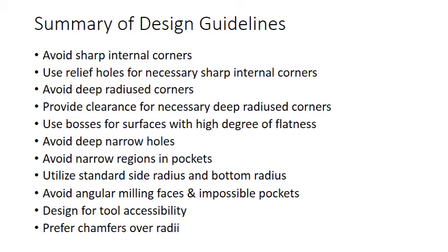To summarize the design guidelines: Sharp internal corners should be avoided. Relief holes for necessary sharp internal corners should be used. Deep radiused corners should be avoided. Clearance for necessary deep radiused corners should be provided. Bosses should be used for surfaces with high degree of flatness.